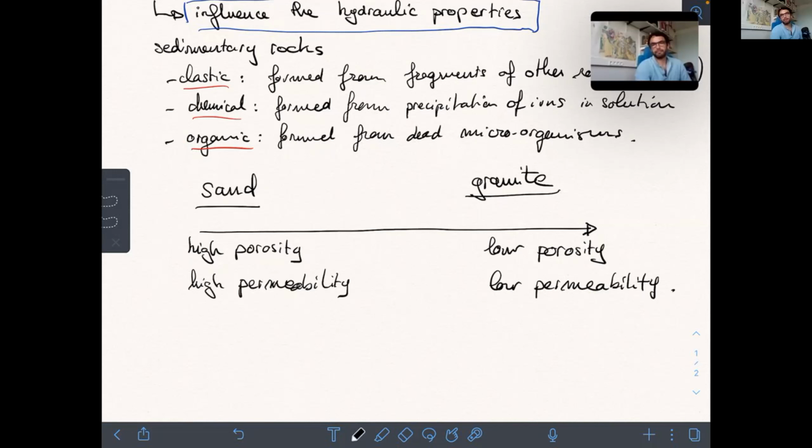So the fluid is going to have more difficulty to go through a porous media if it's highly viscous. So viscosity is actually affecting the permeability. So we have then that the two main parameters that we want to understand are porosity and permeability.